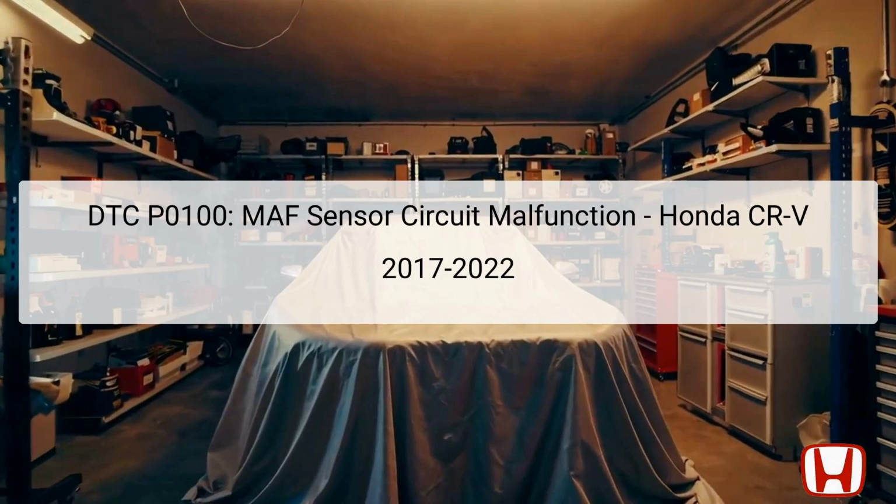The Diagnostic Trouble Code, DTC P0100, indicates a malfunction in the mass airflow, MAF, sensor circuit. This issue typically signals that the engine's powertrain control module, PCM, is not receiving appropriate voltage signals from the MAF sensor or the intake air temperature, IAT sensor. The MAF sensor plays a critical role in measuring the amount of air entering the engine, which is essential for optimal fuel injection and engine performance.